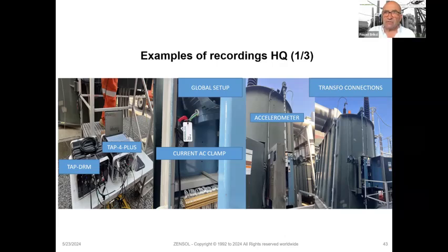So it's for the motor current. So it's really hard afterwards to do the comparison between two tests. So it's important that it has to be the same wires and the same location for the accelerometer. It's why we need to always have the aluminum base put exactly at the same spot and the transfer connection.